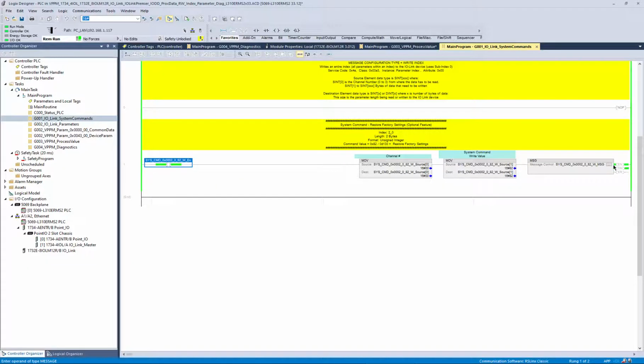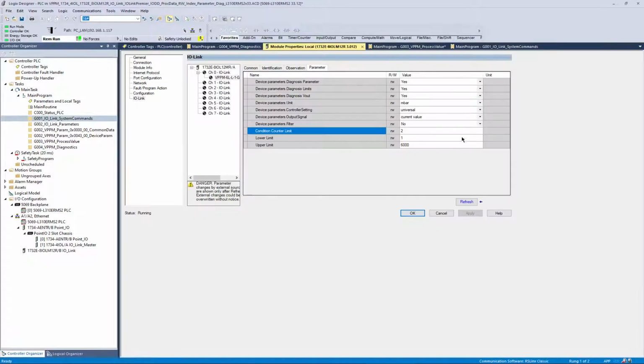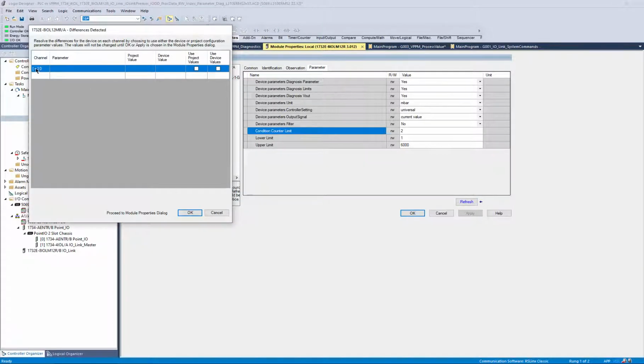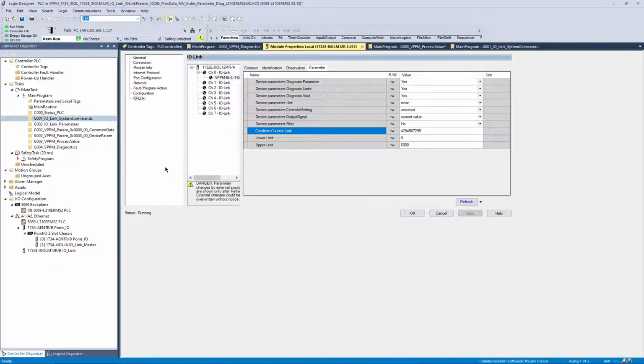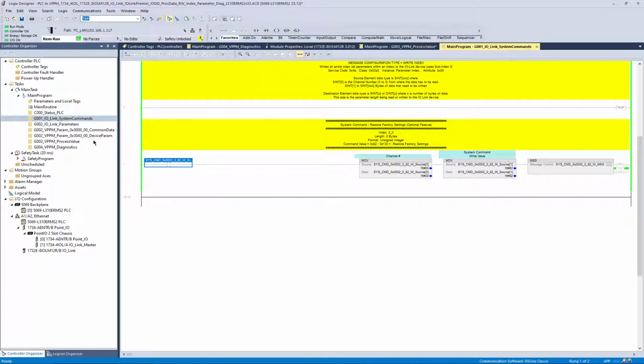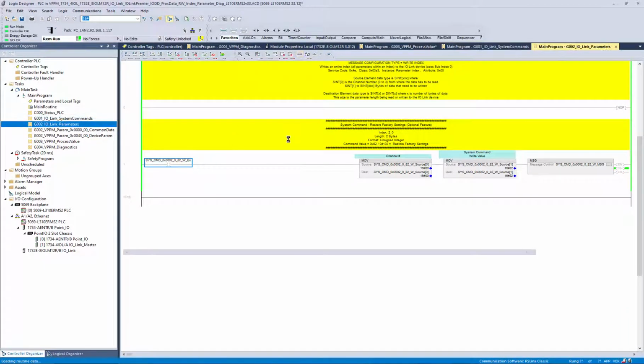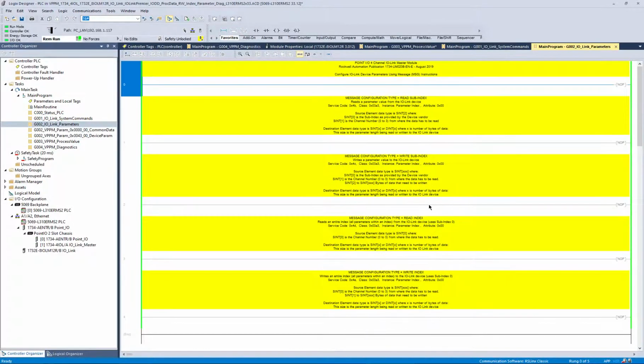we get the done signal. Now when we go back to the device, you will see here that it has reset the values in the device, and I'm going to take those values and put them in here and populate it, and then I hit apply. So that's the restore system settings command, factory settings. Okay, this IO-Link parameters just talks about some individual read and write of index or subindex from the user manuals